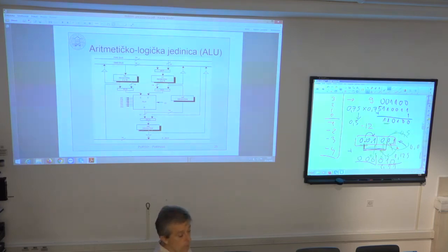And all of this context store and context restore takes cycles, because you have to write these values from registers to memory, to the stack, and later read from the stack back to the registers just to restore the original values that were used in the main program. It takes many cycles if you have to use many registers in the interrupt request routine, because you have to store all the values that were in these registers when the interrupt occurred.